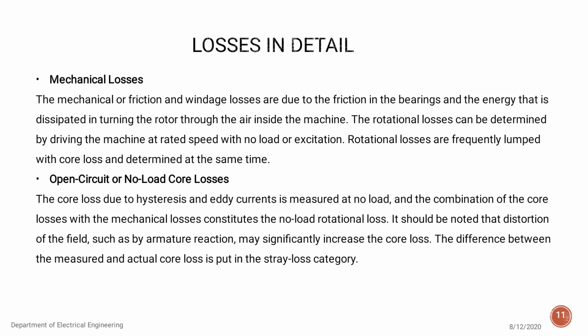If we have to measure the constant losses, which are the hysteresis loss as well as the eddy current loss, or we can say the magnetic or core losses, then and only then can we use the open circuit or no load measurement method.